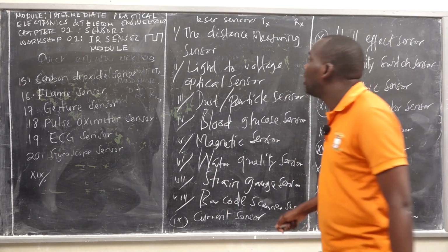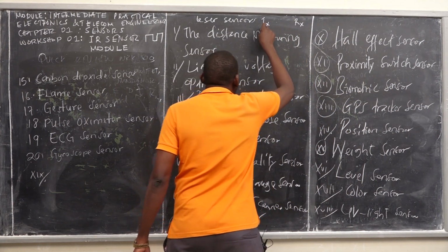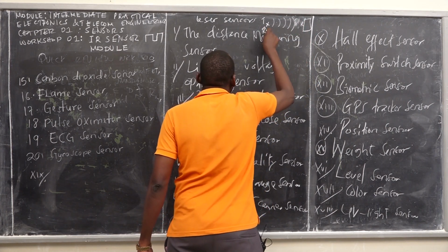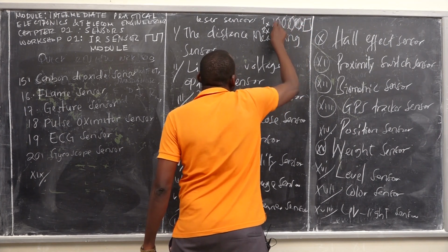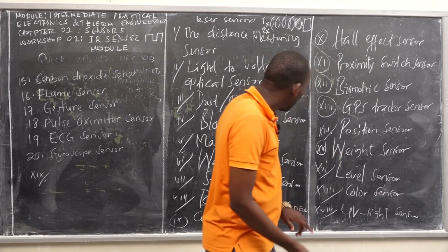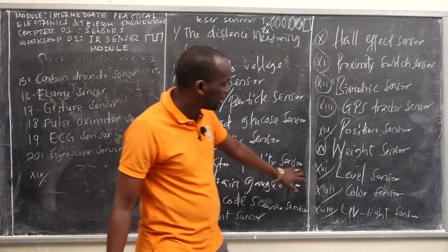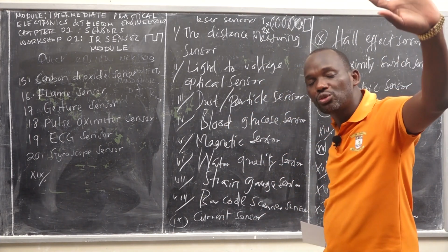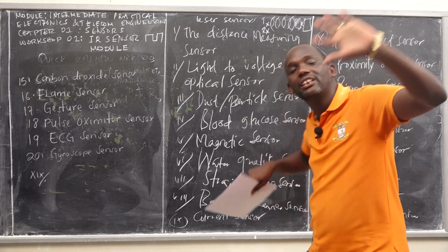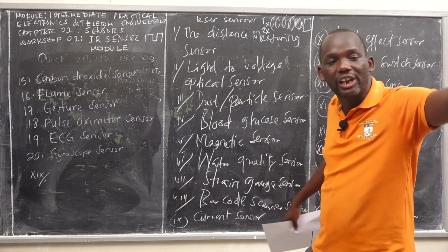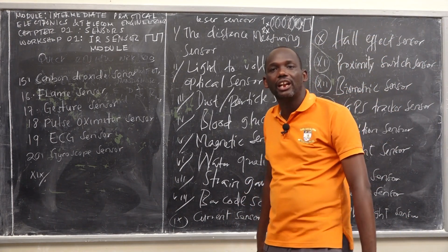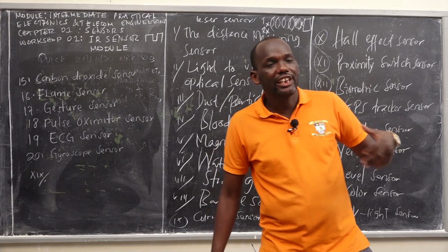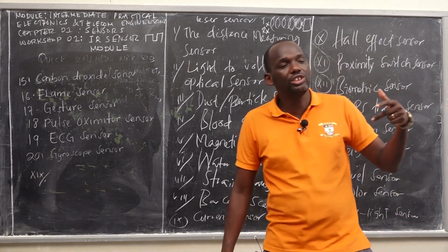Within it, it has a transmitter and receiver. So it just sends the sound wave, and whenever there is an obstacle, because the transmitter and receiver are located in the same position, there is a reflected wave. It's similar to the radar sensor. I think one student, Pili, mentioned the radar sensor. The radar sensor sends electromagnetic waves, which are light waves, to the incoming target. Some of that wave is reflected, received by the radar receiver antenna, and processed. Then it can measure the range. Radar can measure range, determine radial velocity, and determine direction.